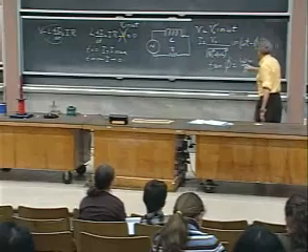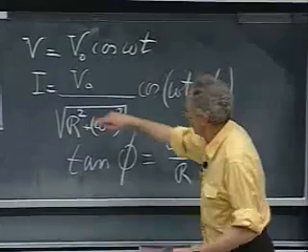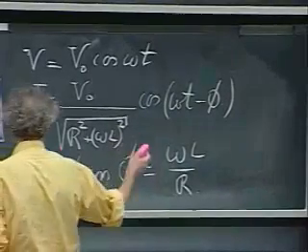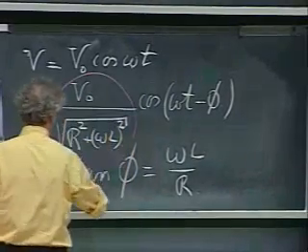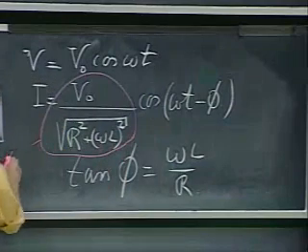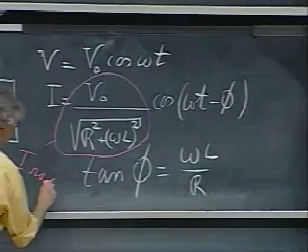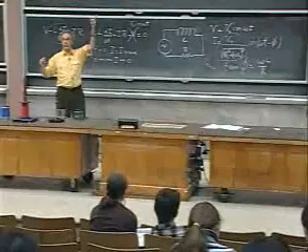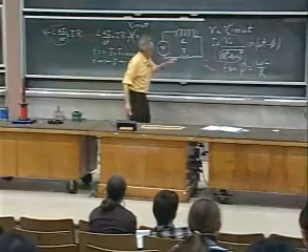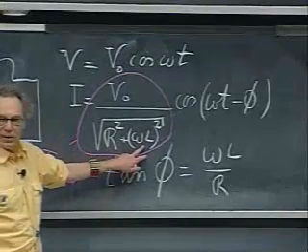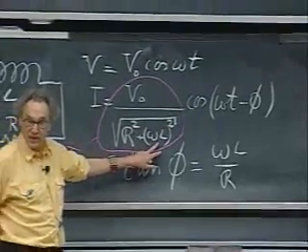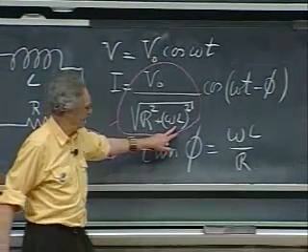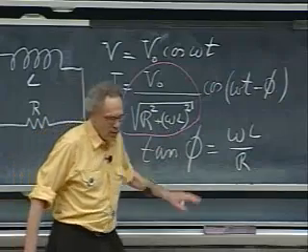If you look at this equation here, then what you have in front of the cosine term is obviously the maximum possible current, because the cosine term is just oscillating between +1 and -1, and so this here is the maximum current that you can ever get. In one full cycle, you get positive and you get negative that value. And notice here the role of omega L really plays the role of a resistance, and in fact, the dimension of omega L is ohms. It really plays the role of a resistance.